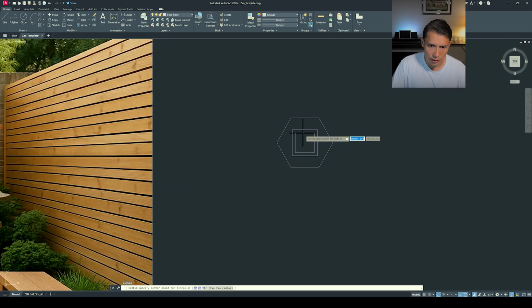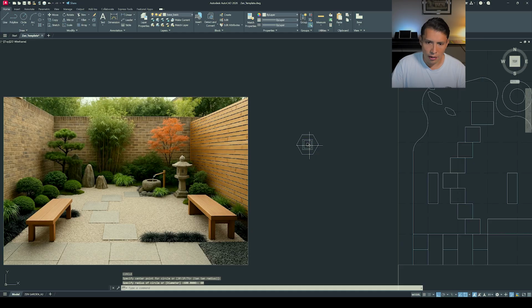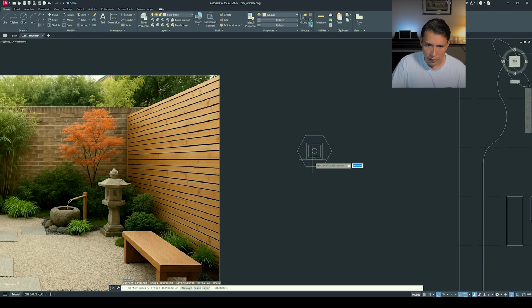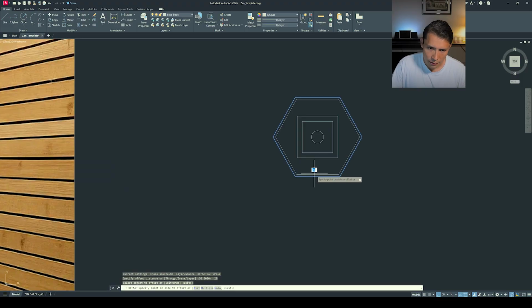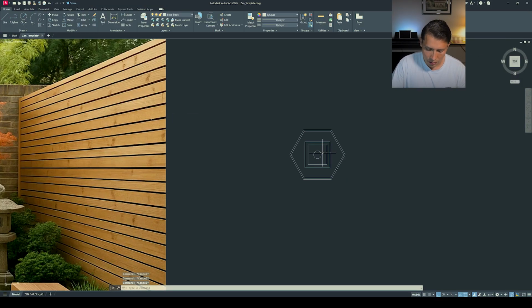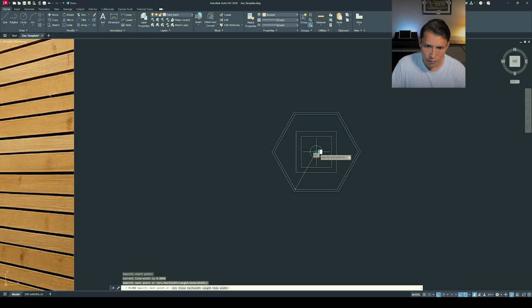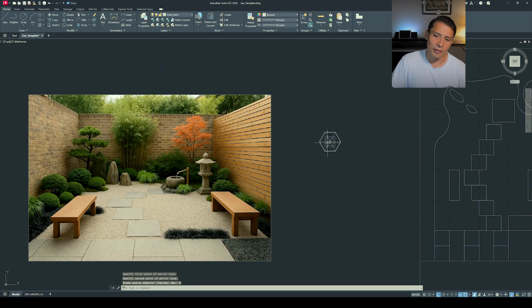We are going to draw this kind of feature that has on the top right here. For doing that, I'm gonna select the circle tool right here, and I'm gonna make this circle 60 in diameter. And just to add a bit more detail, I'm gonna offset 20mm to the inside, and I'm gonna draw a line from this point off to the circle, then from this point off to the circle, from this point off to the circle, from this point off to the circle, and then I'm gonna type the mirror command. I am going to select this line, I am going to mirror them from this point up to this point, and not delete the source objects, which is basically creating a mirror of those lines.